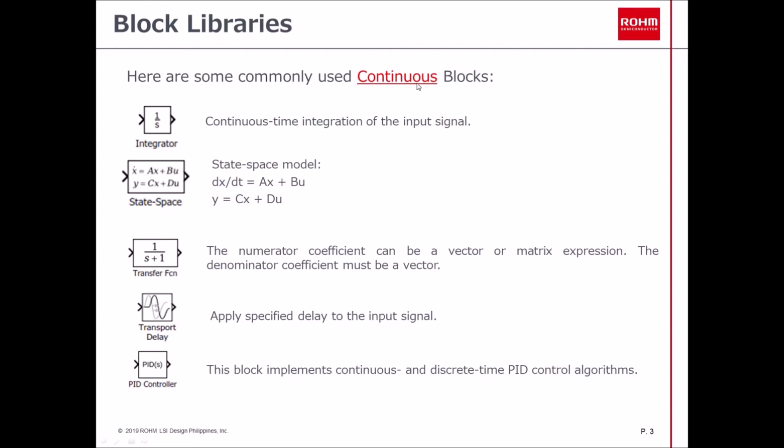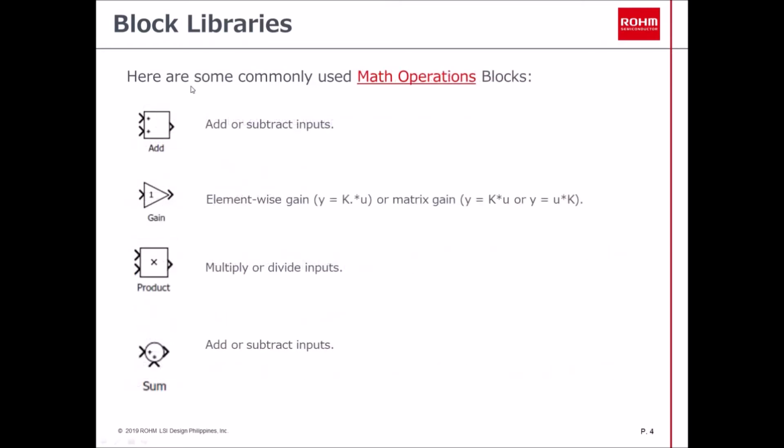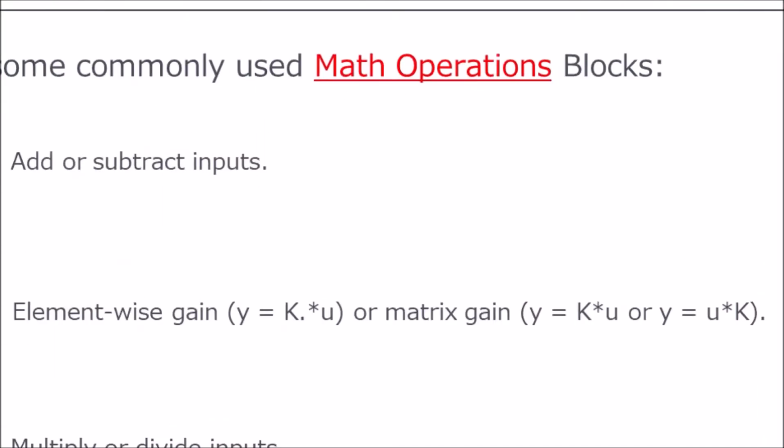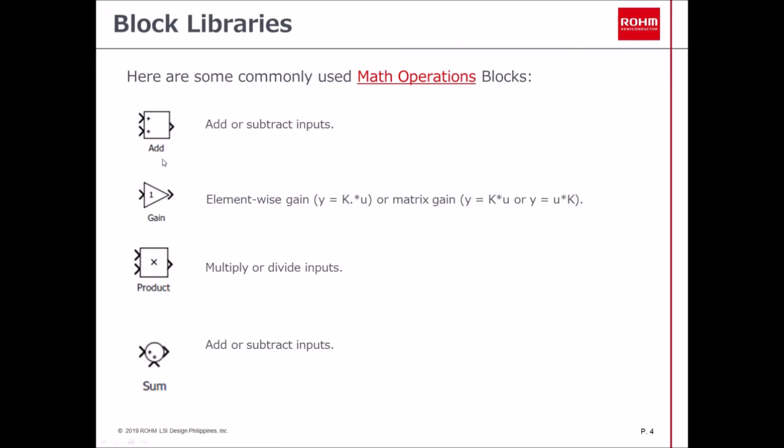Here are some commonly used continuous blocks. Integrator, used for continuous time integration of the input signal. State space model. Transfer function. Transport delay, which is applied to specify a delay to the input signal. And PID controller. Here are some commonly used math operations blocks. Add block, gain, multiply or divide inputs, and sum block.